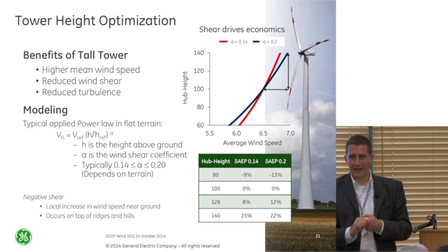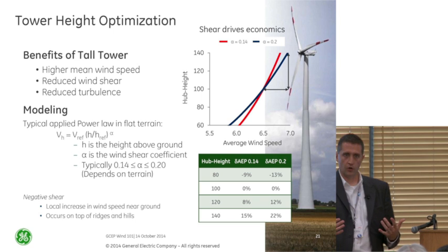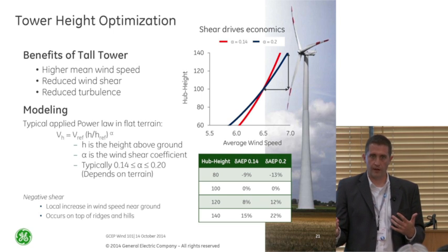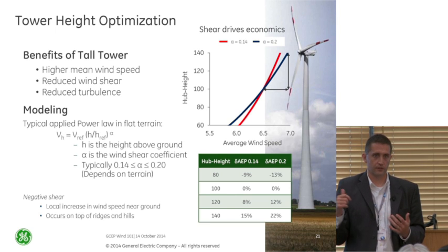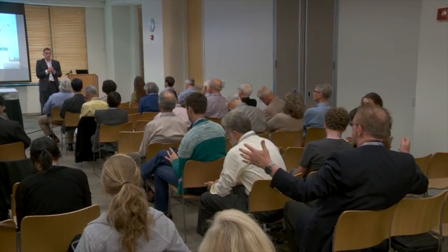Wind turbines are not without maintenance. I mean, they're relatively low operation and maintenance costs, but they're not without maintenance. So you see, do I see any cracks appearing on these things in high fatigue loading type of locations? I asked you particularly about the base, the size of the base and the construction of the base.